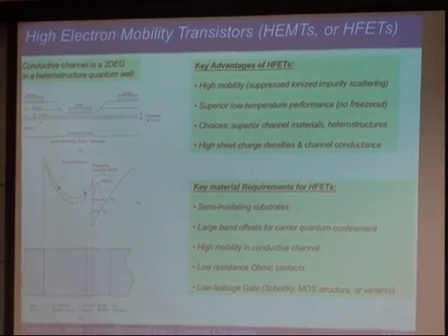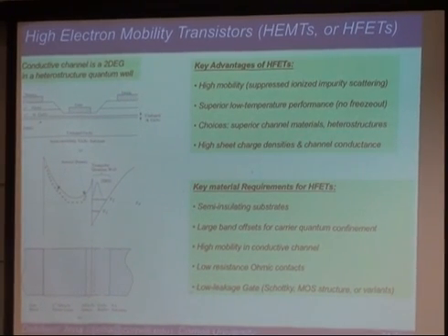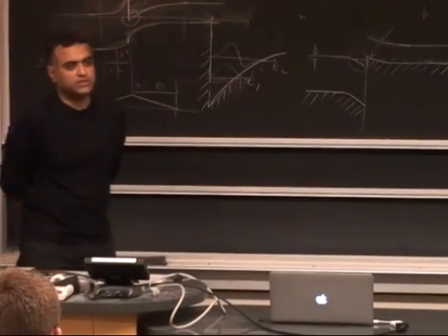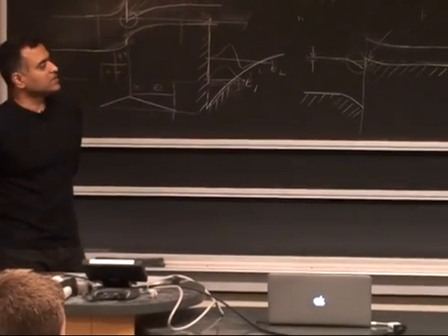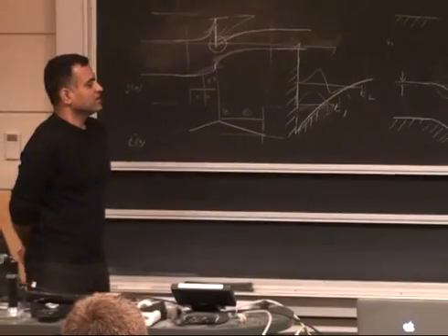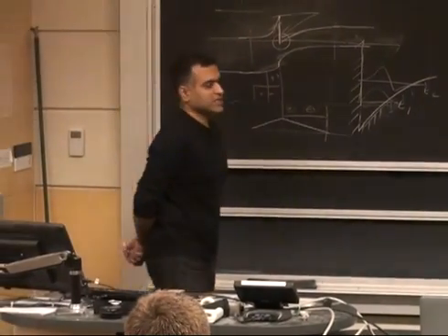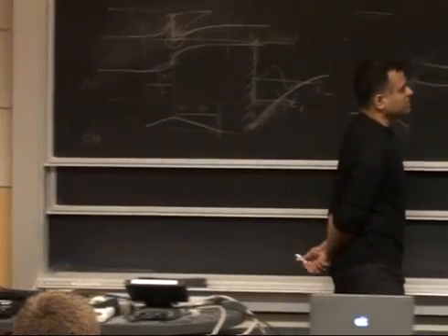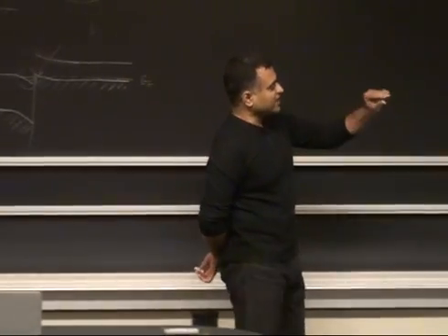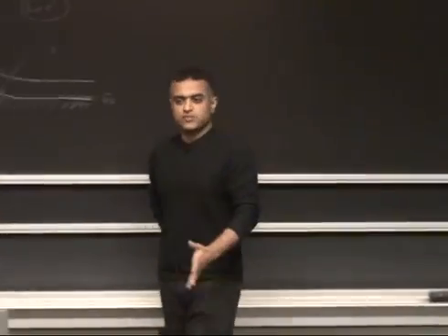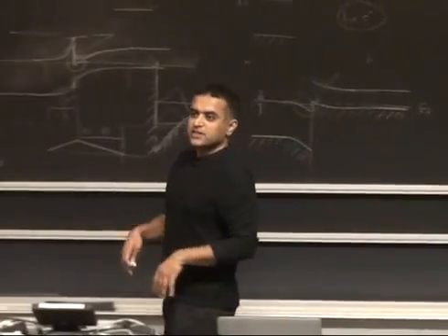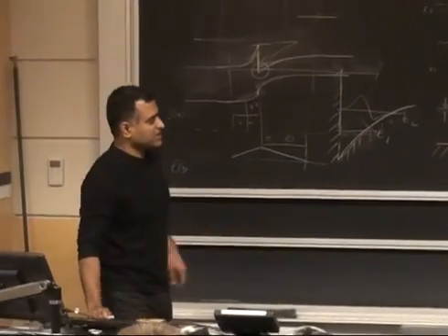So the most standard electronic device, or the most widely used, is the silicon MOSFET, right? And we know that it's not typically considered a heterojunction device, but actually it is, because your insulator, SiO2, has a very different band gap than silicon, right? And now it's a high-K material and other things like that.